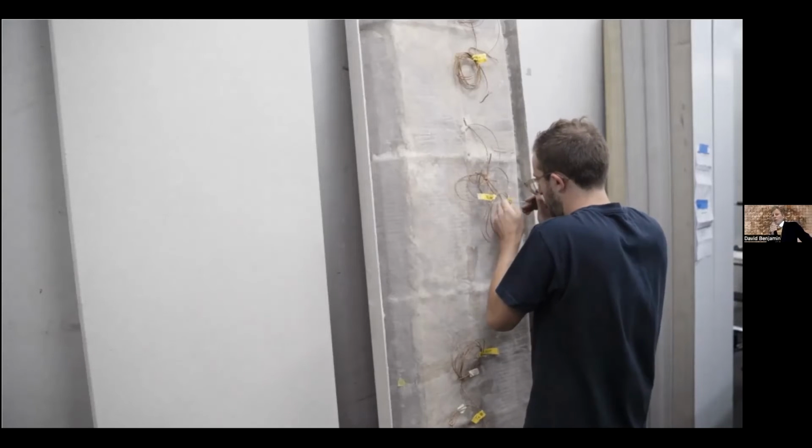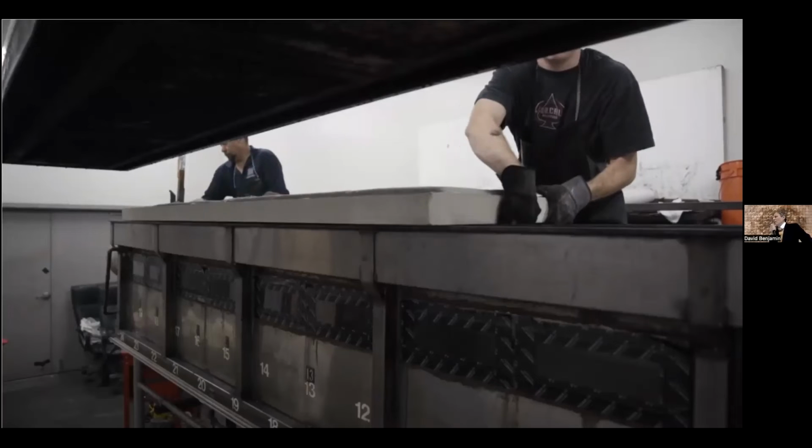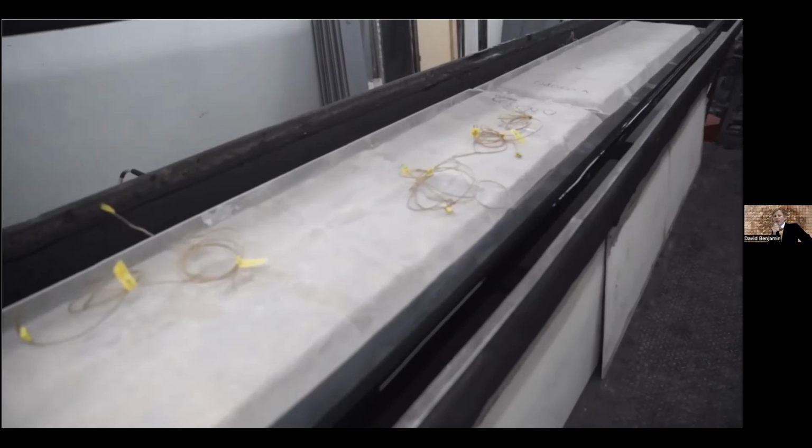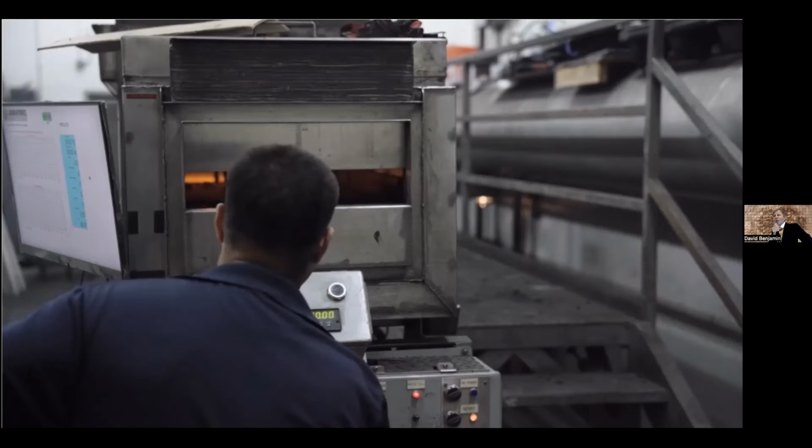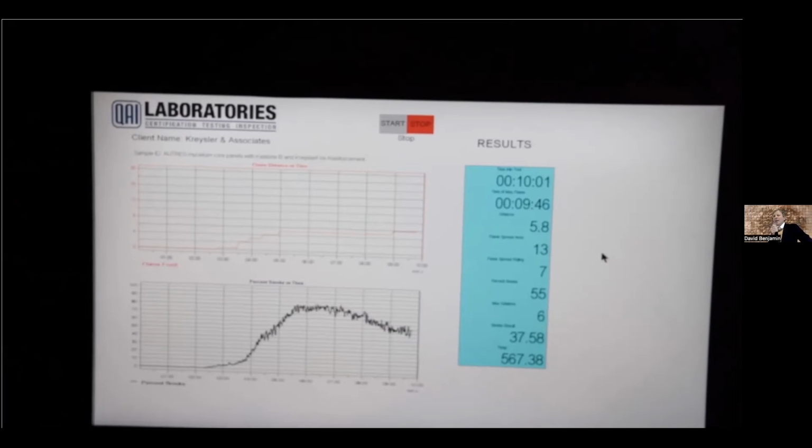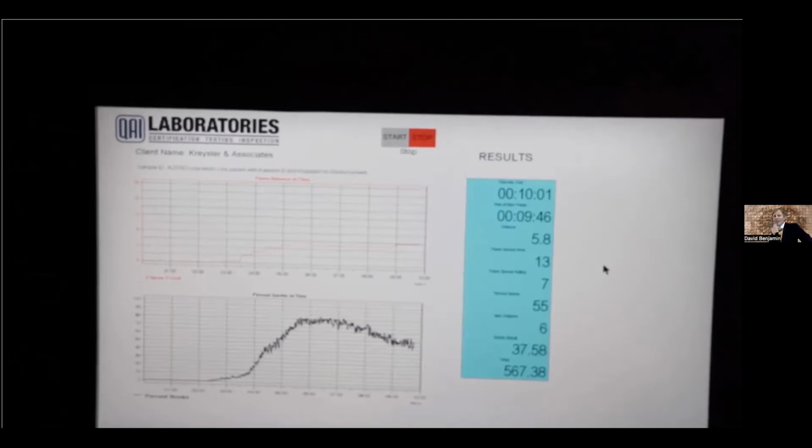We've also been working through other material performance tests to make this real. Here is the so-called E84 fire test, where you create a 24-foot long section of the real material assembly and set it on fire for an hour, basically. And this material system basically received a Class A fire rating. It's basically ready to go in buildings in California, residential buildings under 40 feet tall.